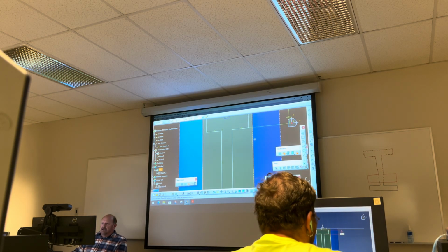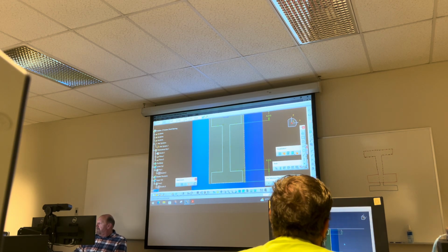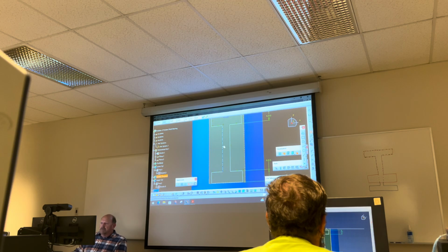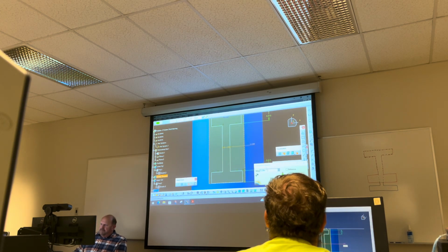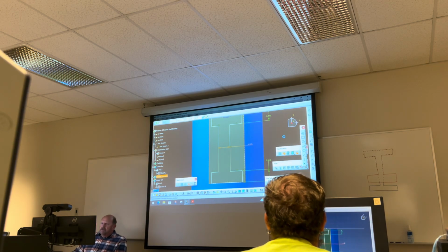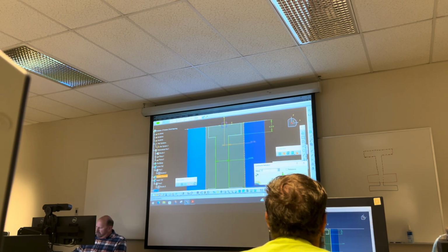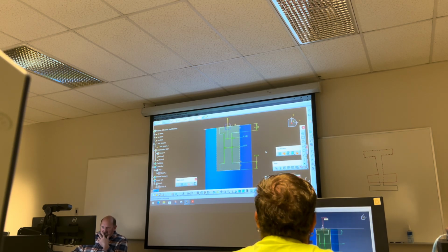Now, if you look at this, you're like, oh, well, it looks like it's on that edge. Well, not necessarily, not yet. The center of this is actually 3/8. So I'm gonna go in here, I'm gonna pick these two. I'm gonna type in 3/8. And then I'm going to make this point to here. So now, as you can see, it's constrained. Those two values are constrained.